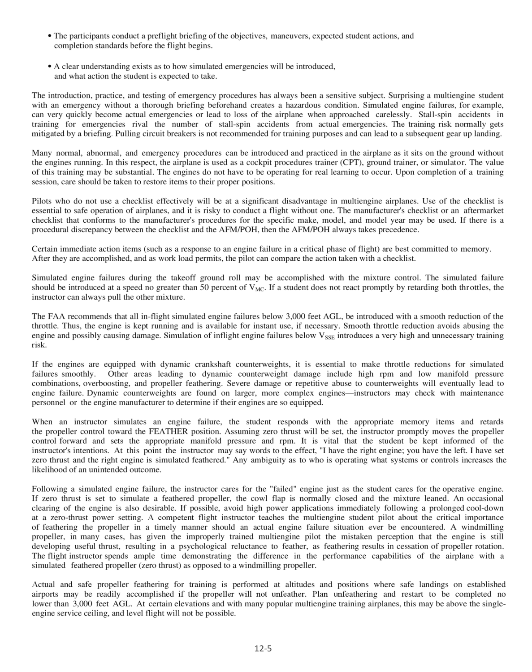Actual and safe propeller feathering for training is performed at altitudes and positions where safe landings on established airports may be readily accomplished if the propeller will not unfeather. Plan on feathering and restart to be completed no lower than 3,000 feet AGL. At certain elevations and with many popular multi-engine training airplanes, this may be above the single-engine service ceiling, and level flight will not be possible.